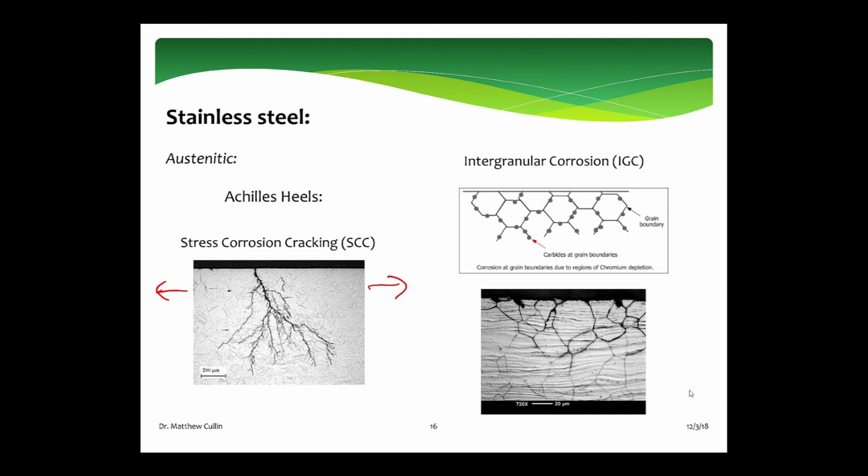So if you're handling seawater at room temperature versus seawater at, I don't know, 100F, you're going to need an austenitic alloy that has a higher chrome, higher nickel content, and it's usually nickel that really helps you in terms of stress corrosion cracking. So yeah, you're going to have to alloy up, and that's about where I'll leave that.